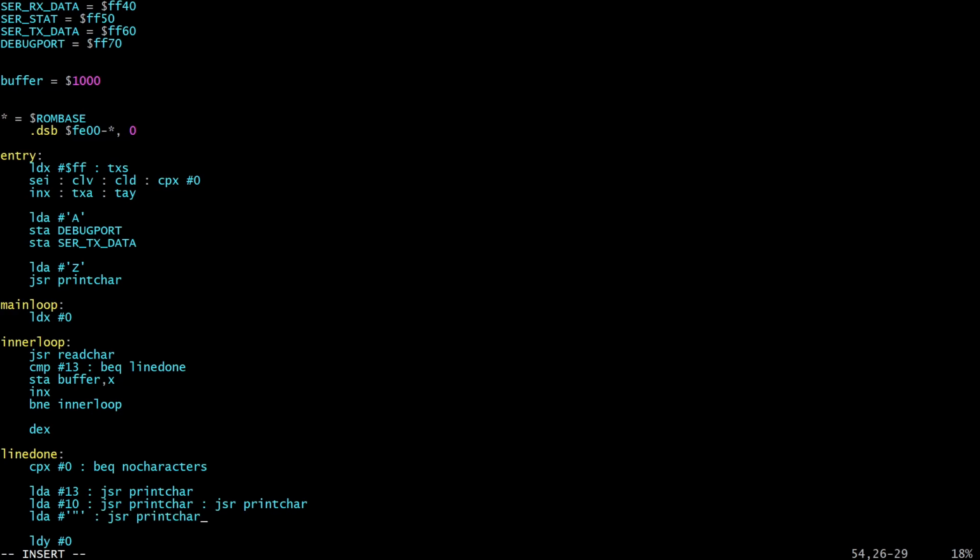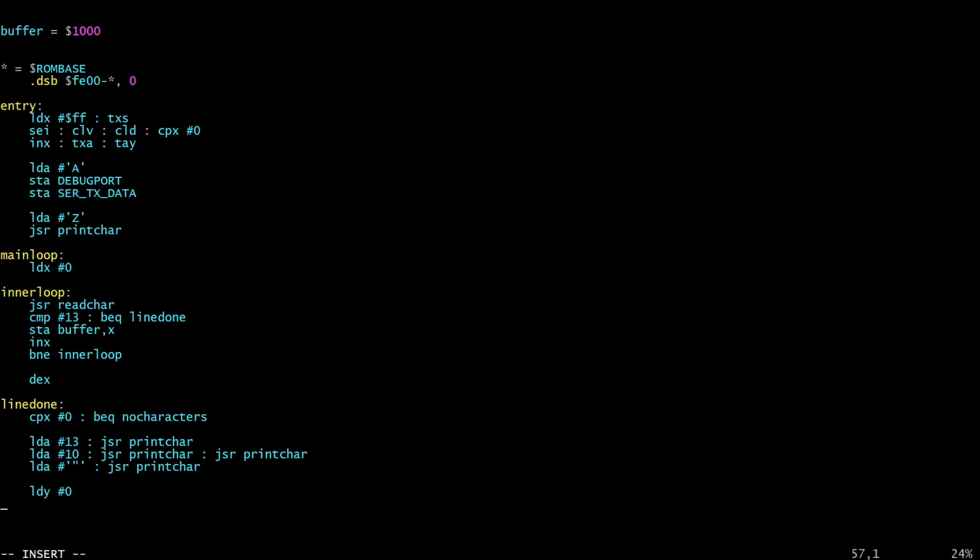Partly because we can, but partly because making these kinds of distinctions makes it a little bit easier for debugging purposes to really convince ourselves that the serial data receive and transmit are working as expected. We should see things like the quotes being exactly on the ends of the string, no junk spaces or whatever in between. There's a lot of ways you can get this stuff wrong, and printing these sentinel characters, as you might call them, can be helpful. So, good thing to do.